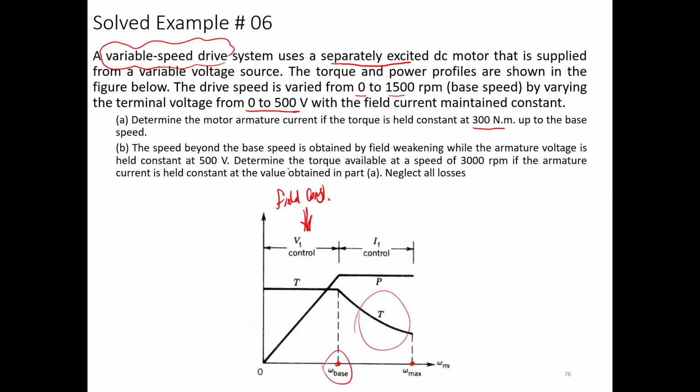So he mentioned that he used field weakening in this part. This is what we call, guys, for this range of control, field weakening. Overspeeding the machine can be made by reducing the field, so we call it field weakening. Why weakening? Because it's beyond the rated speed.